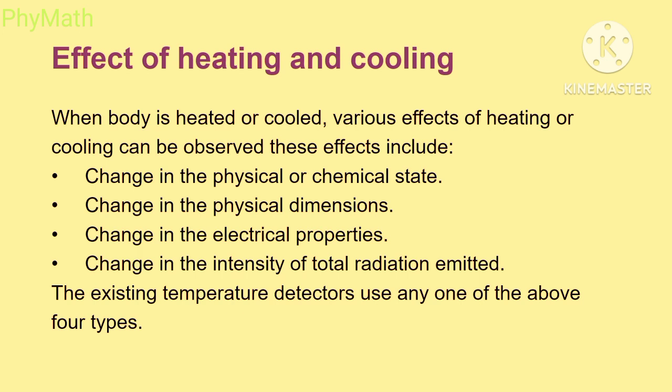Second, change in the physical dimensions. Third, change in the electrical properties. And fourth, change in the intensity of the total radiation emitted. The existing temperature detectors use any one of the above four types, but we will concentrate on the third point, that is when the body is heated or cooled, how electrical properties will change.